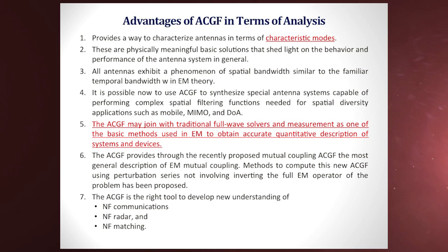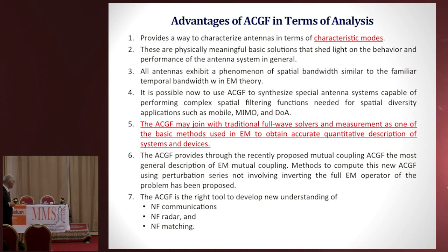And the one in red here, which we expect would have some implication, is that if you combine the antenna current gain function with whatever exists in numerical methods, it would simplify the analysis quite a bit, because you don't have to repeatedly solve Maxwell's equations if you want to do the simulation.